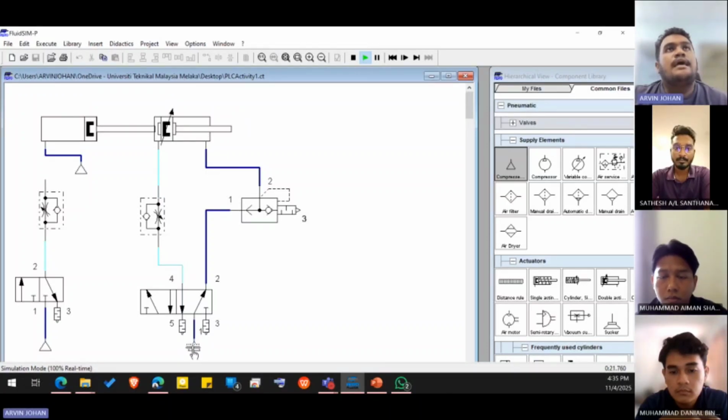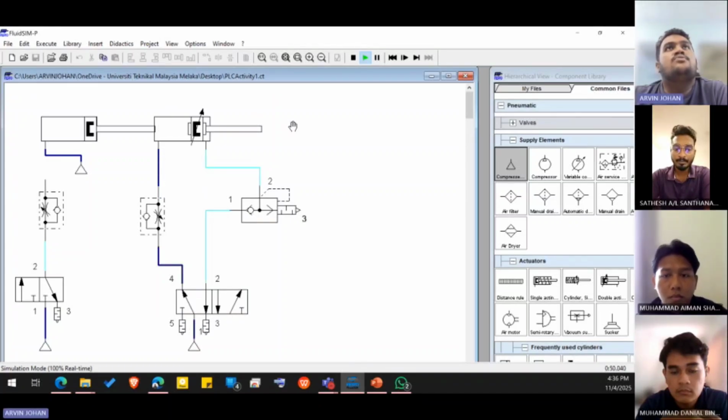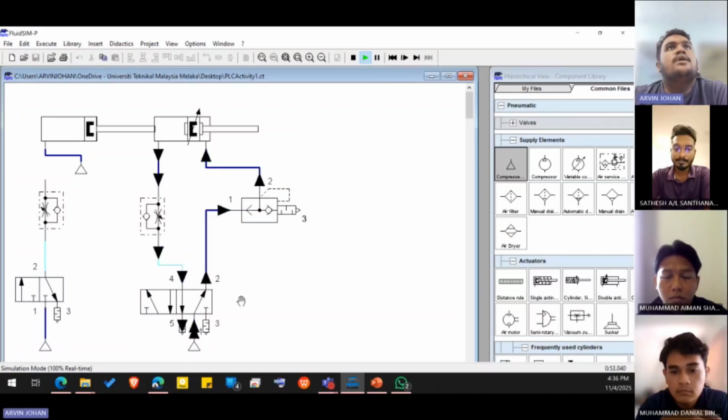When we give it air from the compressor, it pushes out the cylinder, but instead of disconnecting this air supply and the spring retracting the cylinder back inside, we have another inlet in which, once we release the air pushing it, we can also retract the cylinder. So this is the motion when it goes out, and this is the motion when the cylinder is being retracted in. So how does this cylinder get retracted in a slower manner?